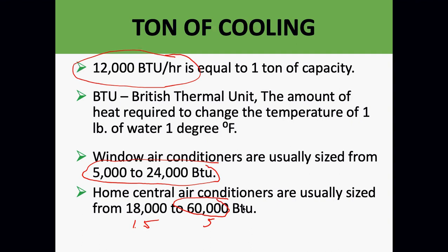I heard the amperage. Okay, that's important because most of our houses only have 200 amp service for newer construction and might have 100 amp service for older construction. What's about phase of power? You're going to need 3-phase power, which you probably won't have available.